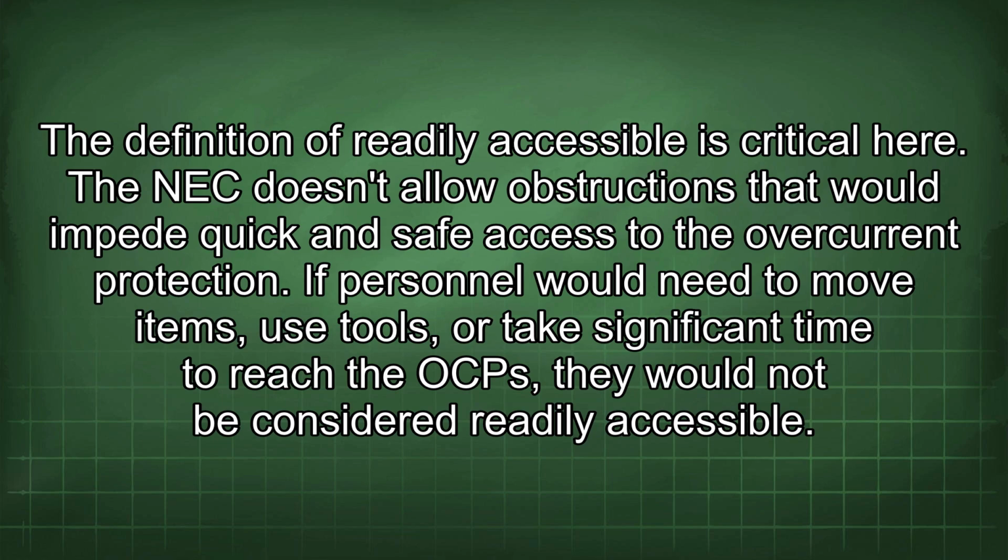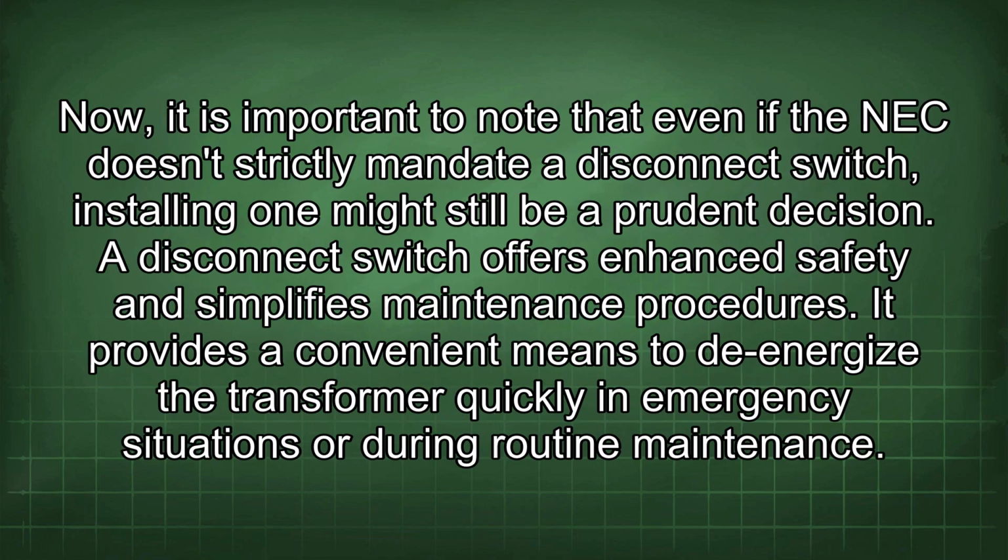The definition of readily accessible is critical here. The NEC doesn't allow obstructions that would impede quick and safe access to the overcurrent protection. If personnel would need to move items, use tools, or take significant time to reach the OCP, they would not be considered readily accessible.